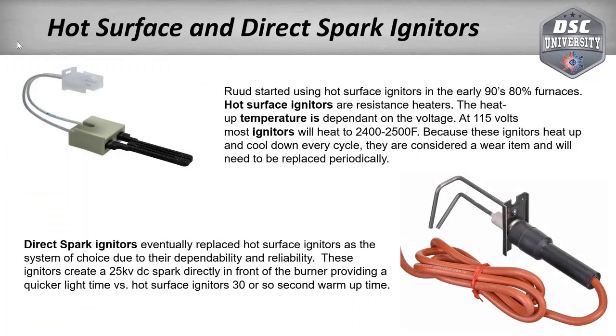Now that we've gotten that far, we've got to light the fire. So we have a couple of different methods for lighting our burners in the furnace. On the top left, we've got hot surface igniters. Hot surface igniters have been around since the late 80s or so.